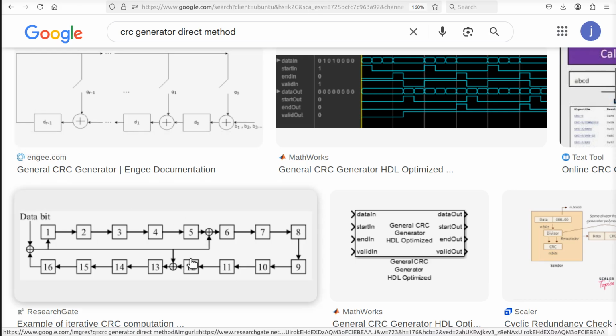In this technique down here, the math is a little bit different. In this case, this is a 16-bit CRC, okay? When you shift in a whole bunch of message bits, after you've shifted in the last bit, you can immediately read the value out of all these flip-flops, and that will equal your CRC, all right? So the only difference in this schematic between the one up here and the one down here is that the most significant bit goes through an XOR gate to all the other XOR gates.